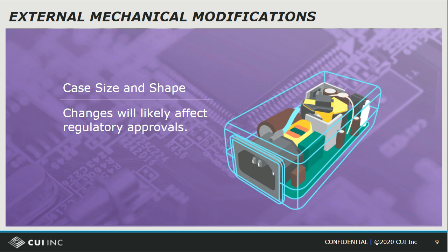The input voltage is already defined for a range of a nominal 110 to 240 volts, and so that hits the majority of the applications. The user may choose to request additional features such as overvoltage protection, overcurrent protection, undervoltage lockout, over temperature protection, or something such as that. Again, I would caution you, typically if you're going to be adding something like that, it turns into a redesign of the power supply rather than a modification of the power supply. And so probably it's a major endeavor.